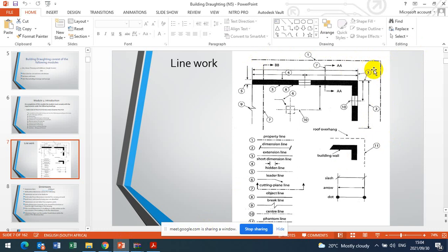Okay. Then we come to a building line. They didn't show us here. A building line comes inside the property line. It's going to be under the boundary layer, but red color. So you don't change the color, just leave it like that. It's going to be a thin center line, like a thin dashed line, we call it. Like this one, but thin. The property line will be thick. It's going to have some corners here. I'll show you on a site plan.